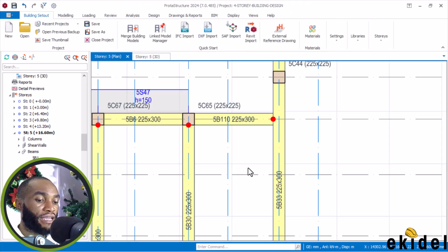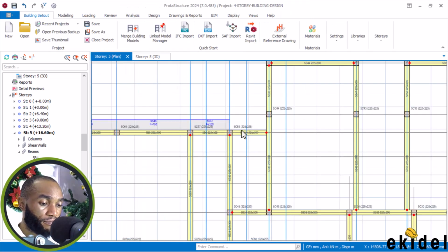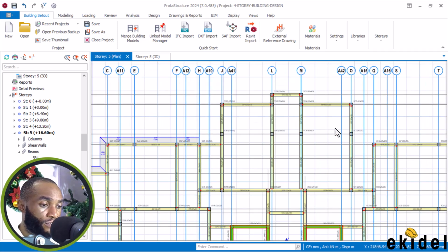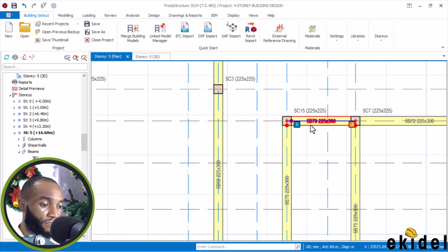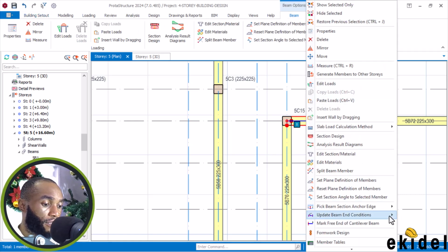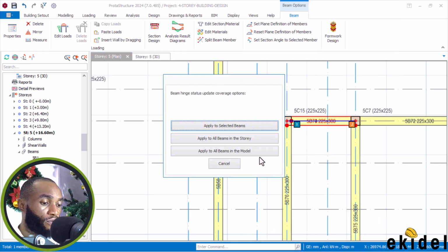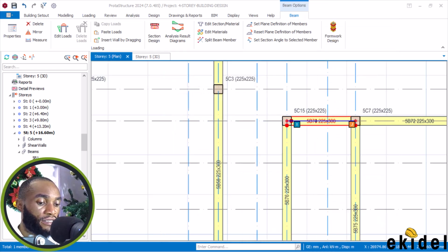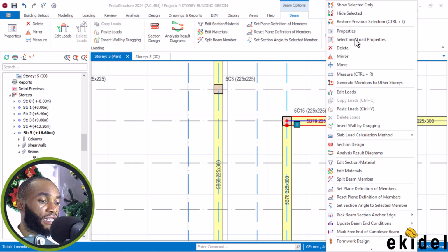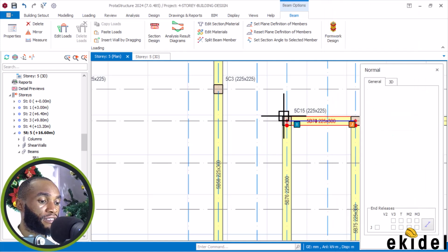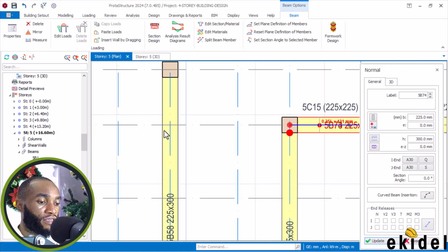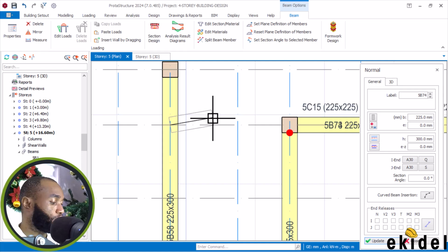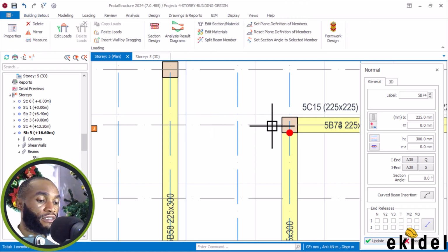Again, right now I'll do the same thing here, just to save time. Click on this, right click here, click on this place here, and remove, say no hinge. And again, click on the beam here, take the beam properties right now, and transfer it from here all the way here, add new beam there. And then what I will do again now is to just finish up.